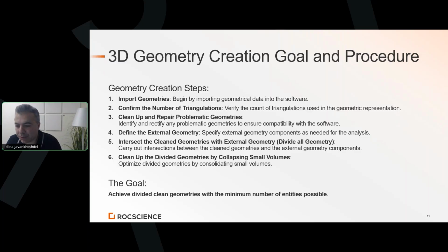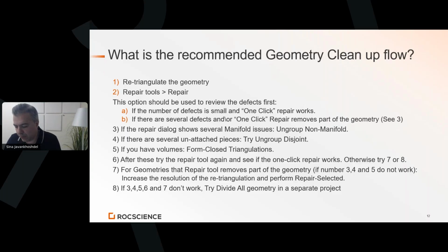Keep in mind, Slide3 cares less regarding bad geometries compared to RS3. In RS3, your geometry needs to be clean enough to be able to mesh the model and compute and converge the model. But in Slide3, as long as you are able to create a 3D model, you can compute it with much less problems. Now, we talked about the cleanup part. There are 8 steps that you can watch in our previous webinar on the YouTube channel of Rock Science.